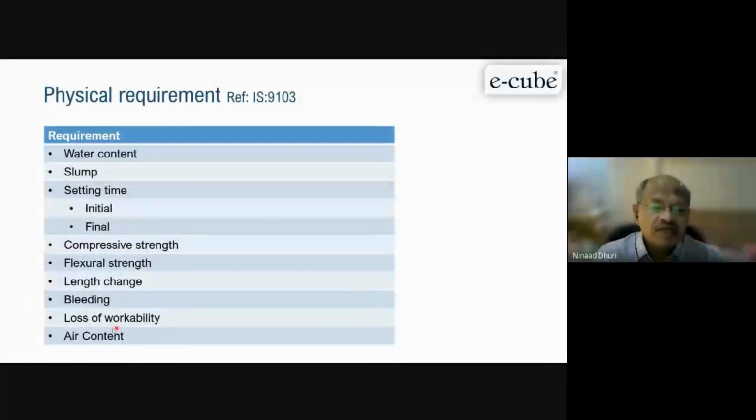Loss of workability you have to check, because certain admixtures may give immediate flow, and within a certain time, maybe within half an hour, there is a drastic drop, which is not good for concrete. Whether we are using RMC or otherwise, a certain minimum time is required for handling concrete.